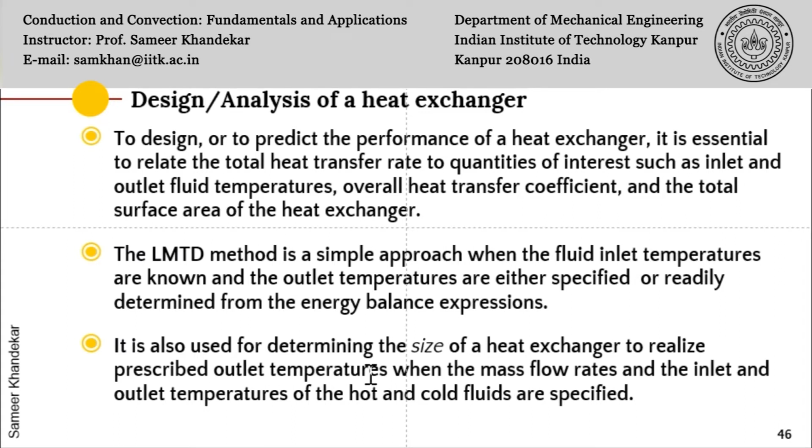So for example, if you know the inlet temperatures and for a given size of heat exchanger, the outlet can be predicted. But then if that doesn't satisfy the client, then you need to increase the area so that there is more residence time inside the heat exchanger, and so you will get the desired outlet of either the hot fluid becoming colder or the cold fluid becoming hotter, whatever is the main objective function. You achieve that by the sizing problem. So this is how you will proceed. Let us try to understand it more clearly in the next slide, which is slide number 47.